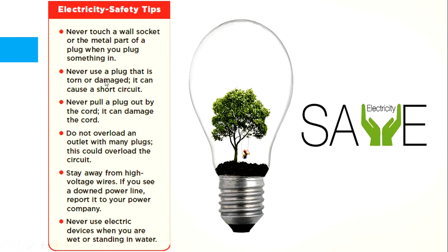Don't use a plug that is torn or damaged, because this can cause a short circuit. This can cause problems. Never pull a plug out by the cord. It can damage the cord. Do not overload an outlet with many plugs. This could overload the circuit, so you should check how much load a circuit can bear. If you overload it, it is going to cause problems.